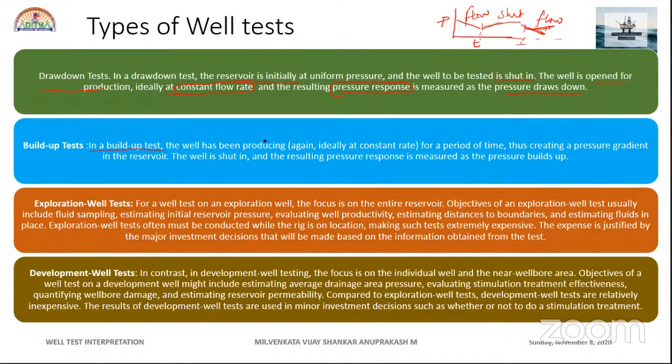In a build-up test, the well has been producing, ideally like your drawdown test, at a constant rate, thus creating a pressure gain in the reservoir. The well is shut in and the resulting pressure response is measured as the build-up test. What we can get from your build-up test is the wellbore behavior regarding the wellbore storage.